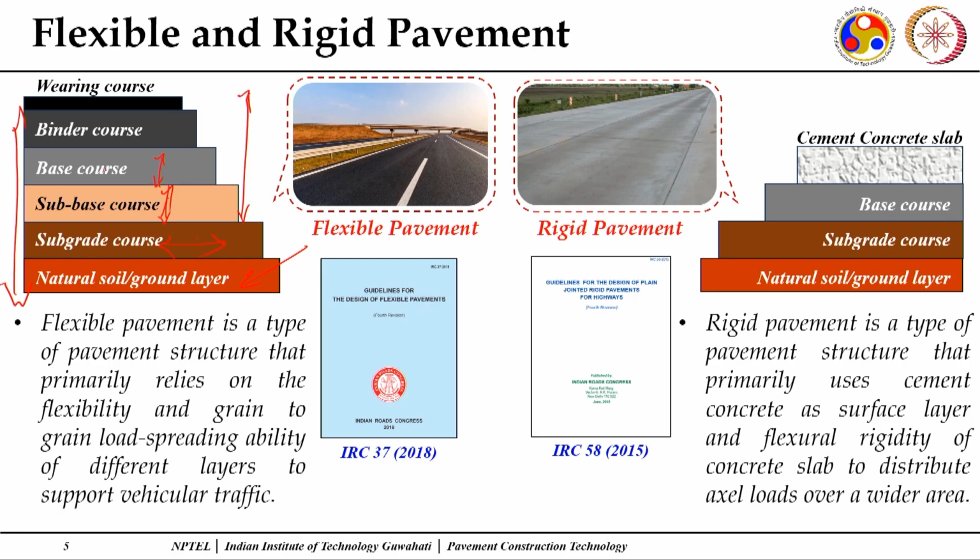You might have read that through fractional distillation you can extract different products. From the distillation of crude, where we get diesel, petrol and other products, the residuum which you get is your bitumen. Bitumen is used as a binding material in the binder course and the wearing course. Because of this binding material, they have good strength compared to your unbound courses.